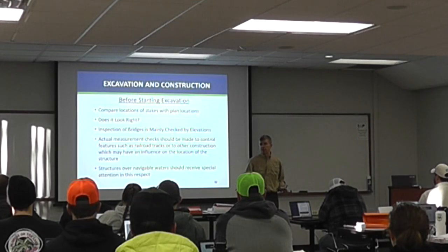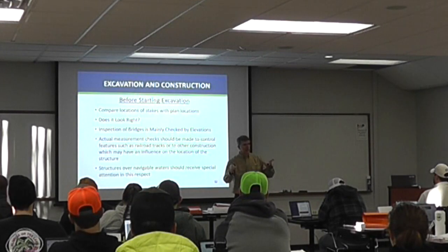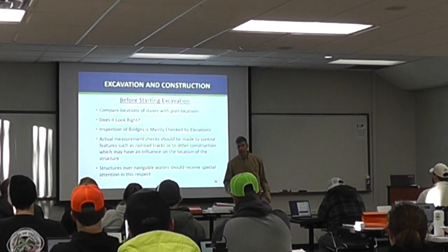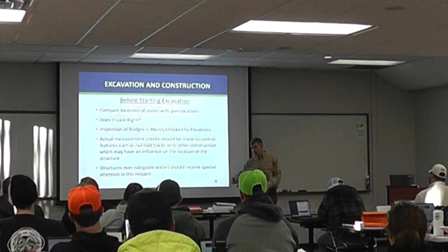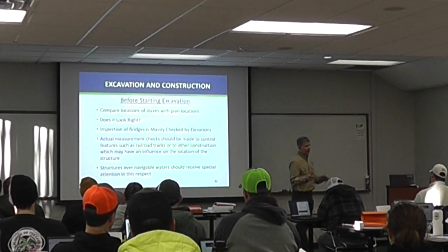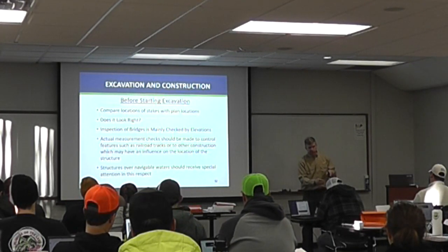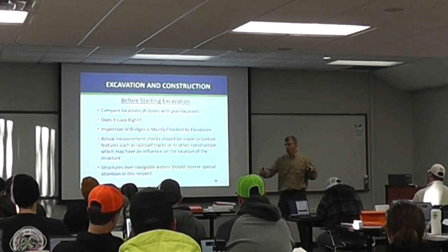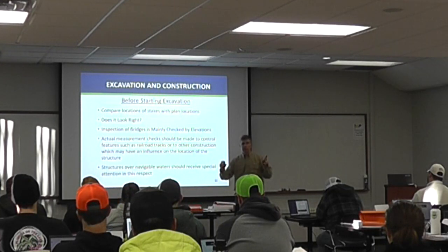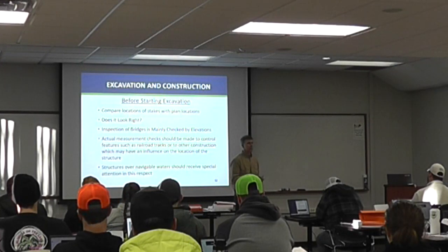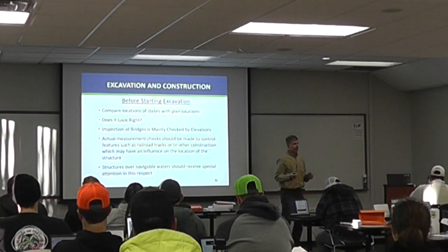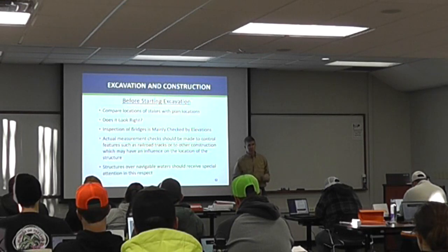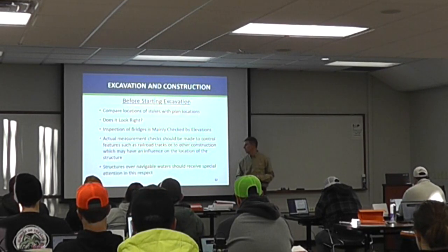Well, it turned out there was a plan there, and there was a 3-foot offset that somehow was missed. So pier 2 literally got built 3 feet off. We went in and had to undermine the pier, put in a little shear lug, drive a couple extra piles, scab onto the pier wall that had already been built, and then we were able to build the superstructure in the correct location. But again, as you're going, if you can, keep your eyes open, look for alignments and things